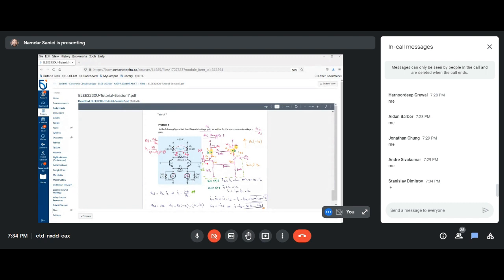So for the differential voltage gain, you can split it into halves, while the center of this little RE is ground, as well as the center of this RL is ground, because the potential across these resistances, this RE and the RL, are opposite to each other with the same magnitude. So somewhere at the middle, the potential has to be 0, right?